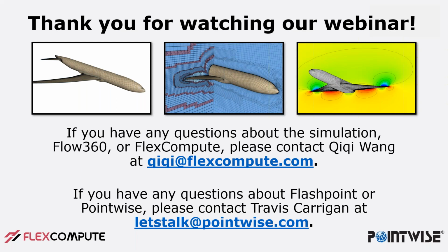So like a wing root, concave corner, you don't want a quilt that consists of both the wing and the fuselage and kind of smears over that concave corner. You want to be able to have a nice hard boundary there, and so you need to have the quilt boundary terminate at the wing root junction.